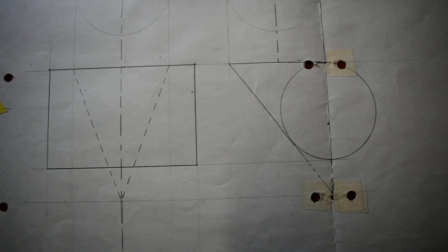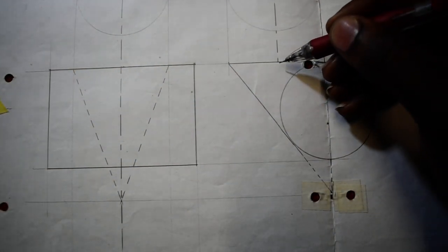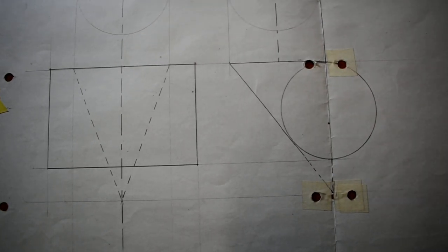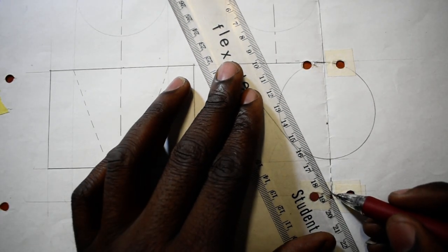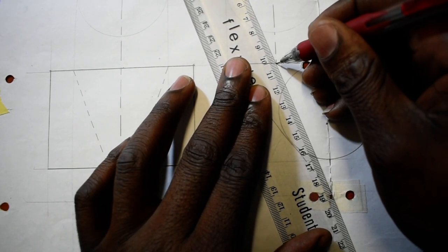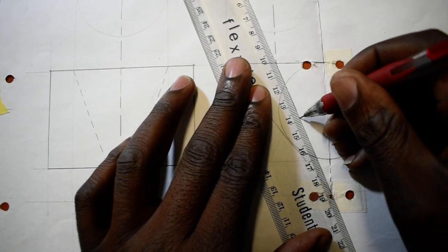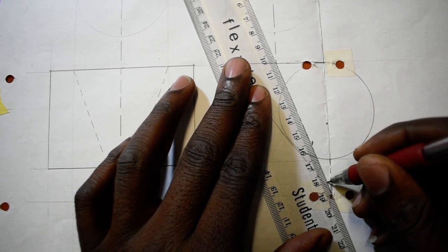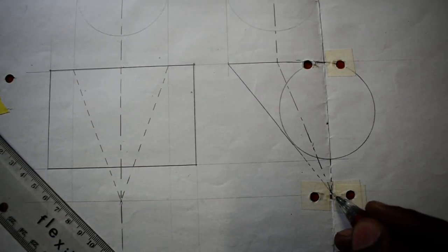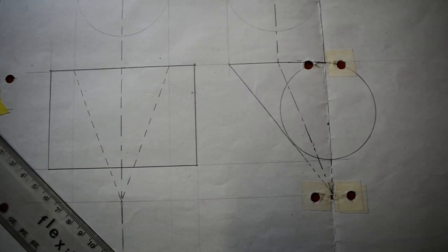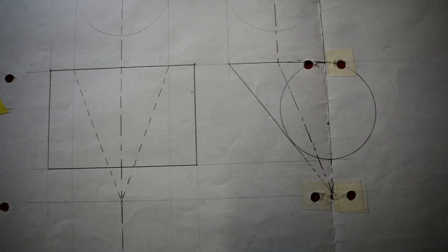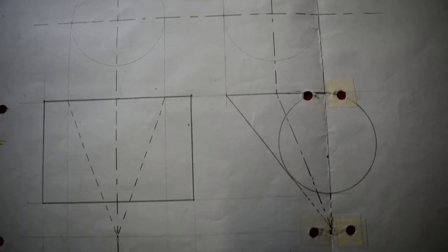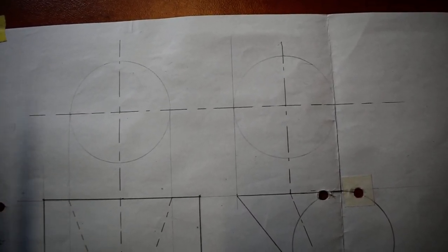So now we are going to approach drawing the line of interpenetration. But now let me take this center line, because once it touches there, it's supposed to come to my apex point. That goes as a center. There is my apex point. Right. So let's divide our circle into 12 equal parts. We've got two methods of dividing the circle into 12 equal parts, isn't it?